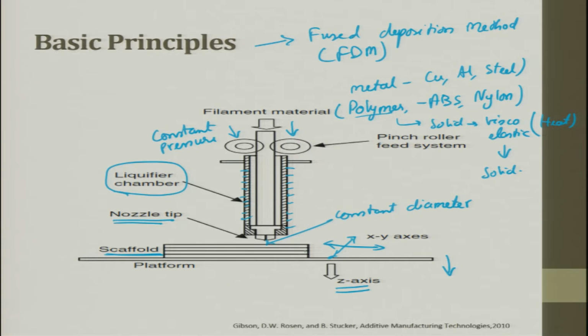So here the feed rates, the constant laying feed rates are dictated by the table movement. So there has to be a synchronization between the pressure with which it exits out, or the way it exits out, and the speed in order to get a uniform rod thickness.